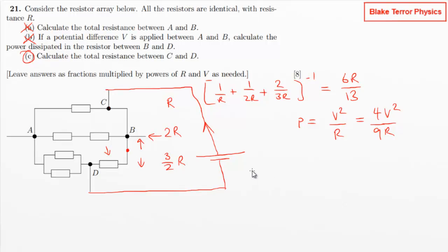Because you see people trying to apply, going around thinking about Kirchhoff's laws and things like that, and thinking, well, how do we go around this circuit? We could go through here, and then what? Are we going back up here? Is that where current's going? I mean, that is a path from C to D, where we go to the left through this single resistor here. Then we go to the right down the middle branch, and then we go to the left down here. I mean, that is certainly a path from C to D, at least in terms of following the wires. Is that a valid path in terms of the circuit and the way that the current might flow? Well, we're going to see no, it isn't.